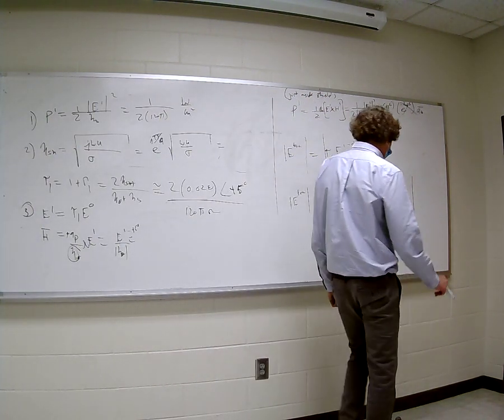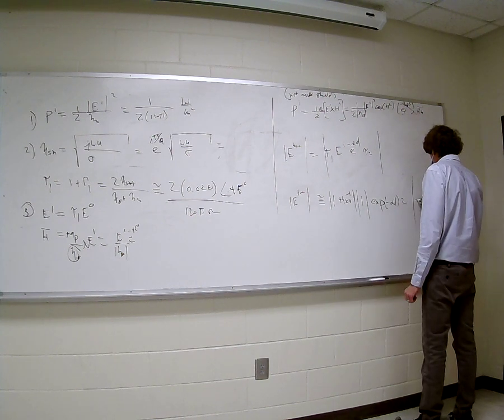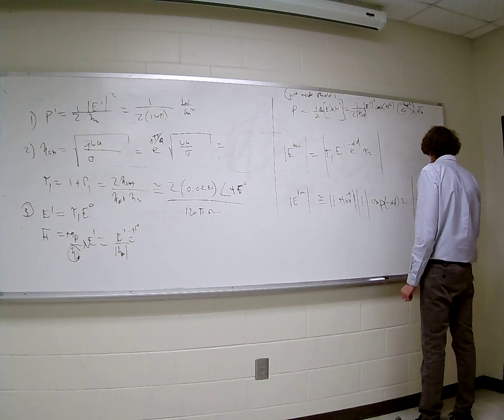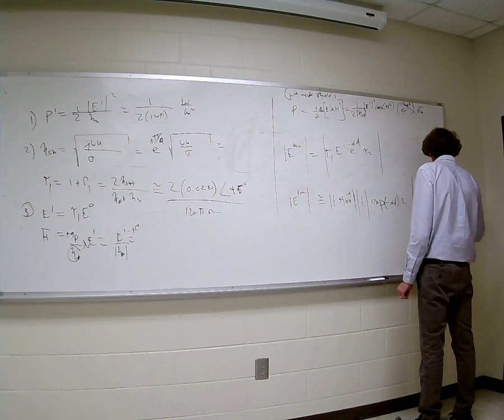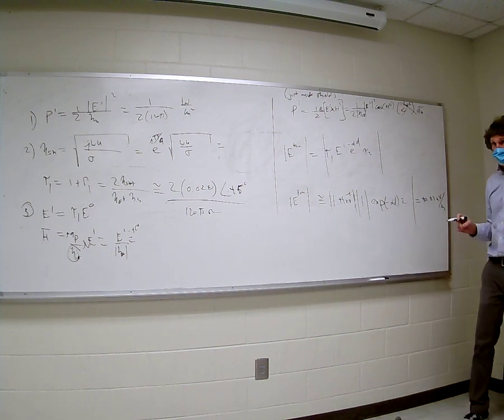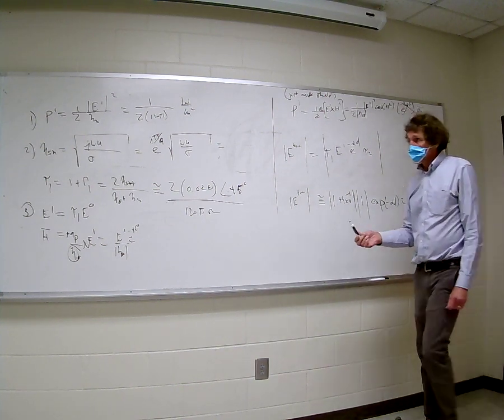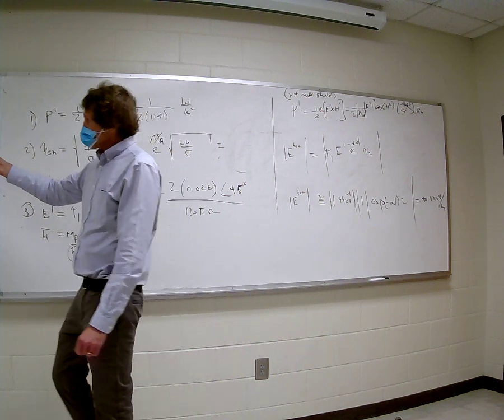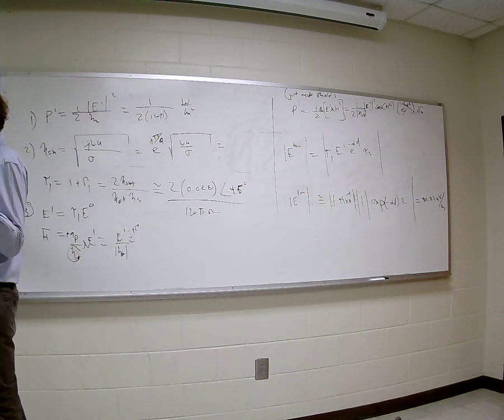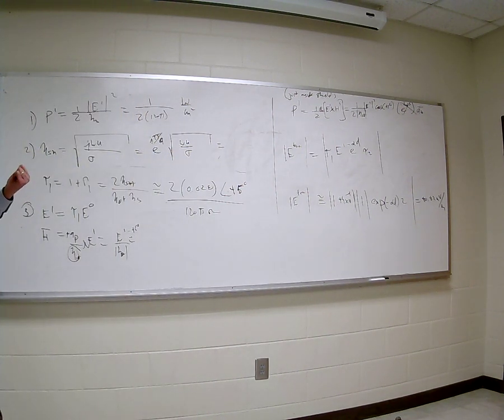So this is 40 microvolts per meter. Agreed? Now that's the field just on the other side of the shield. That's how much is coming out. Now look at the magnitude reduction. That's almost, what is that? That's better than 5 orders of magnitude, 5.5 orders of magnitude, correct, class? It's down by 10 to the minus 5th. That's a huge amount of reduction, correct? That's the electric field.